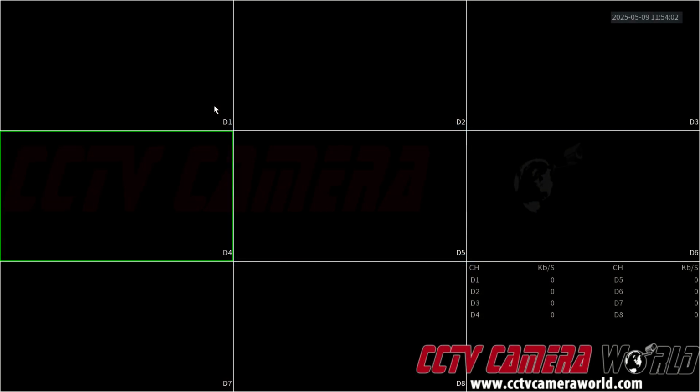In this video, I'm going to show you how to modify or change the Wi-Fi channel that your Wi-Fi NVR is broadcasting if you're having issues with your cameras connecting, or if your cameras are dropping intermittently. This is usually due to the fact that when Wi-Fi is broadcast, it uses a channel, and if you're in a residential area or a commercial area with a lot of Wi-Fi networks, those networks are often competing for bandwidth or for the frequency that the radio is on.